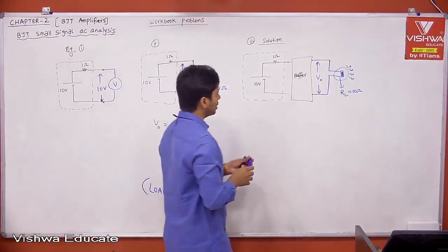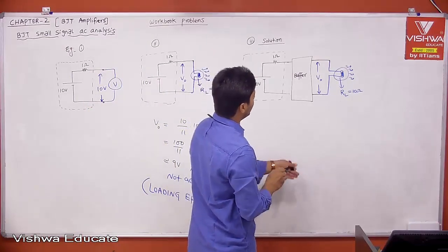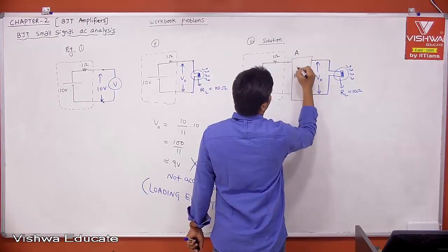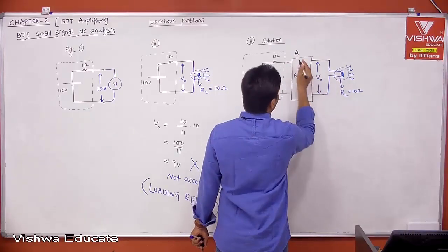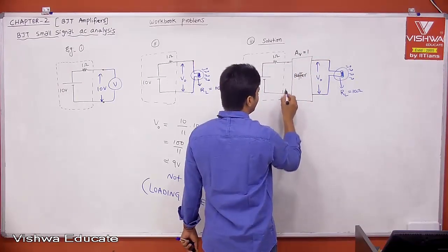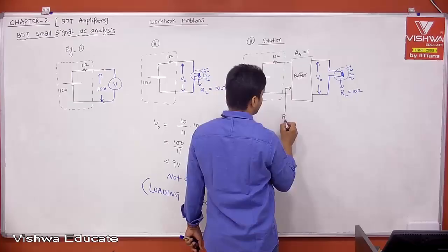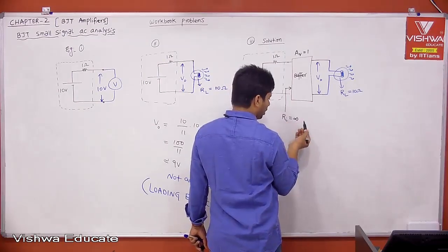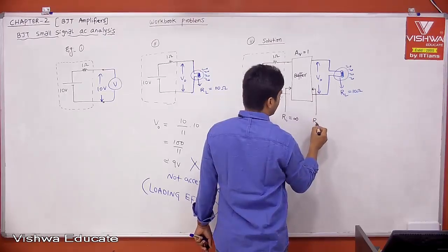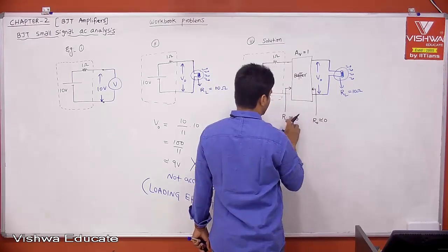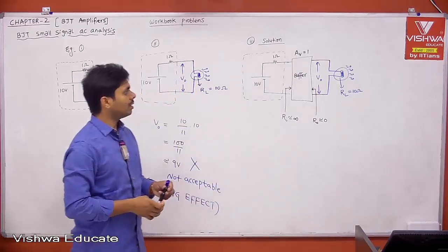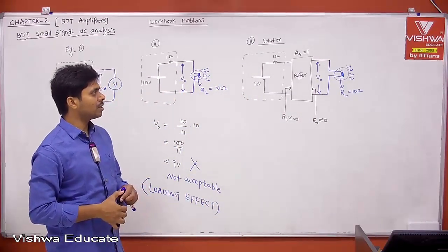Let us say the voltage gain of the buffer. Voltage gain in the sense that it passes the signal as it is. Buffer is nothing but buffering. Therefore, the voltage gain, let us say, is 1. And the input impedance, let us say, is almost infinity or very high, and the output impedance is almost 0. Having these things, let's see what our V0 is.